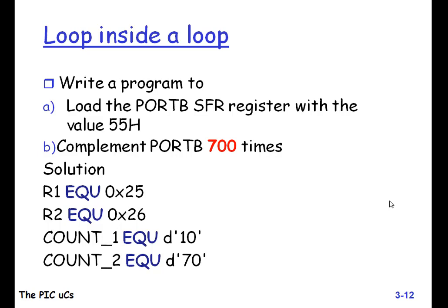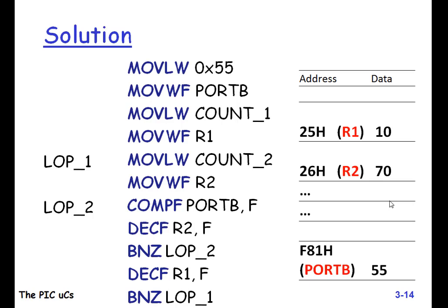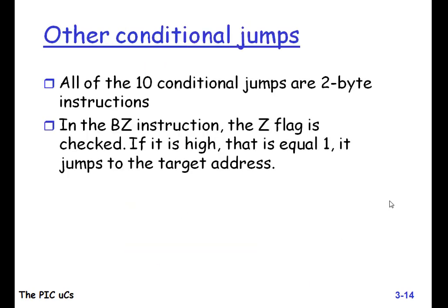Another topic is a loop inside a loop. This is a program in which we load the PORTB SFR register with the value 55H, then complement PORTB 7 times. The solution is given, and it works one by one, line by line, and the output is given on the right side for your ease.